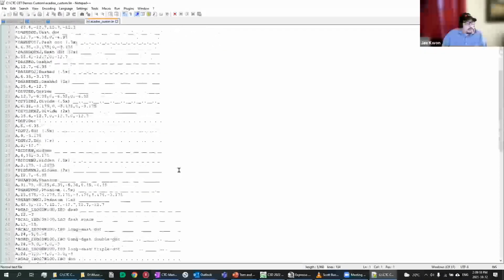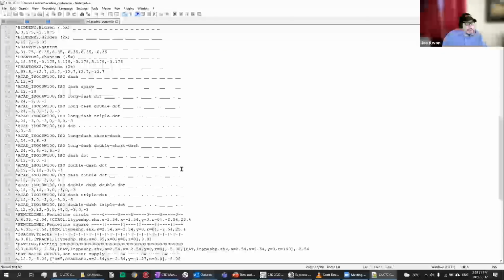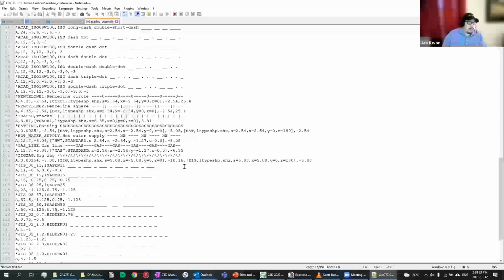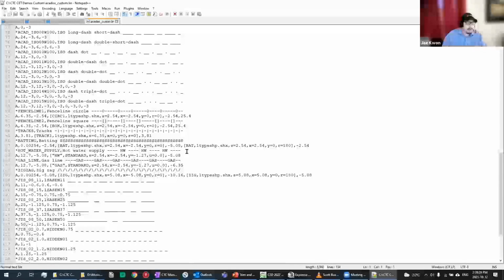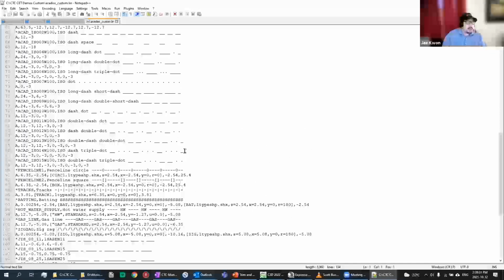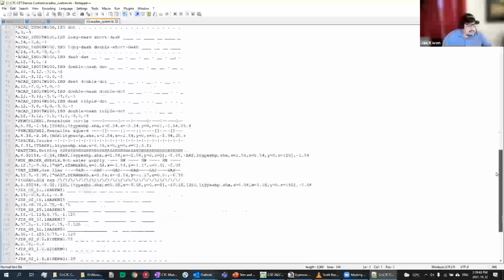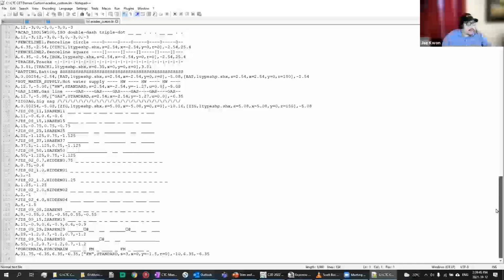Out of the box, the way we manage our line types when it comes to the specific style is basically just through some kind of text editor. Your support file folder has a .lin file that you might customize and add your own linetypes to. Usually there's a custom section near the end.